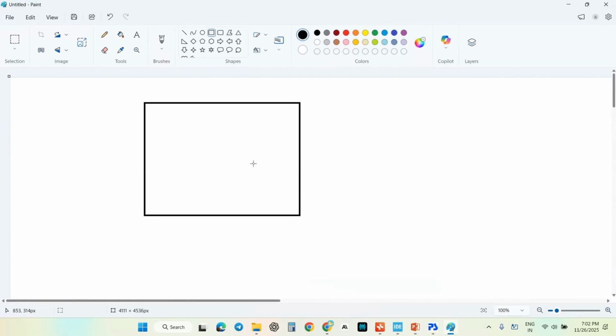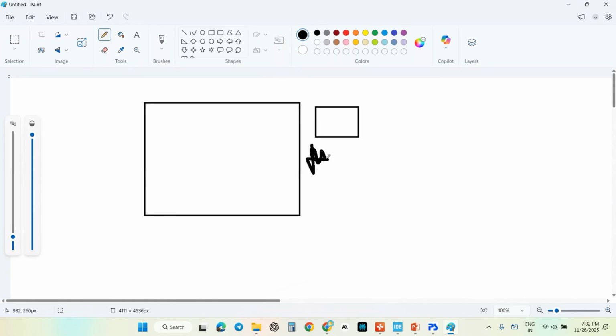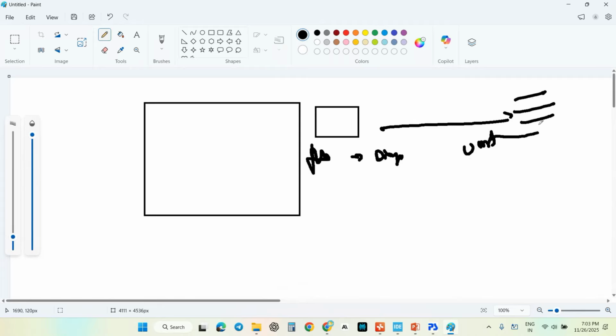Yesterday we did one project, the ADC temperature logger system. That system collects the analog signal as digital data, and that data is transmitted to the other microcontroller through UART. Each piece of data is sent after some delay: the first data, then after a 1 second delay, another data, and after 1 second, another data. This is the basis for the data being sent properly.